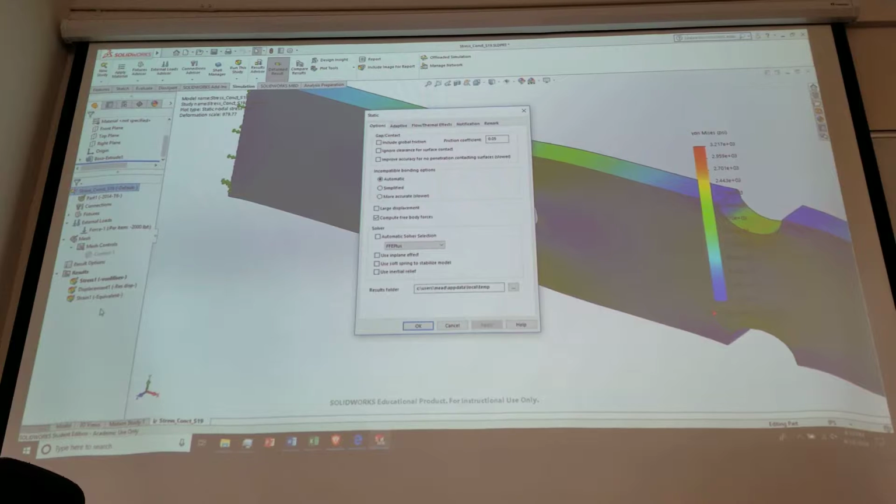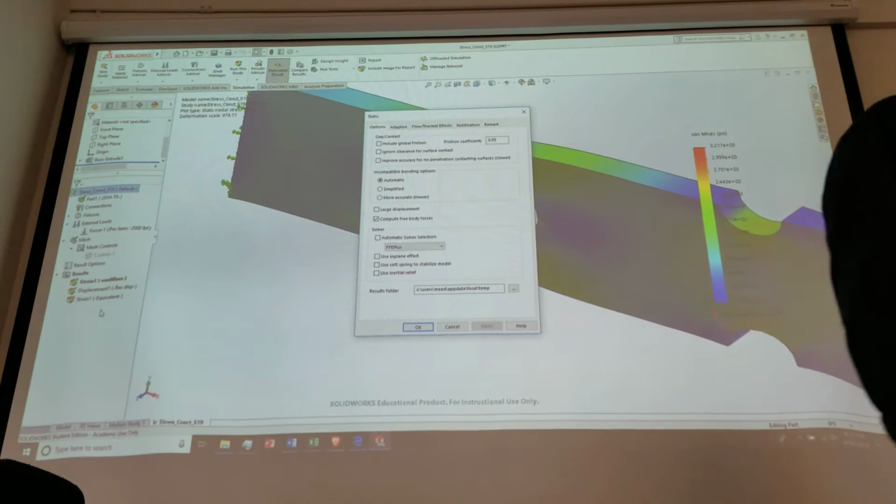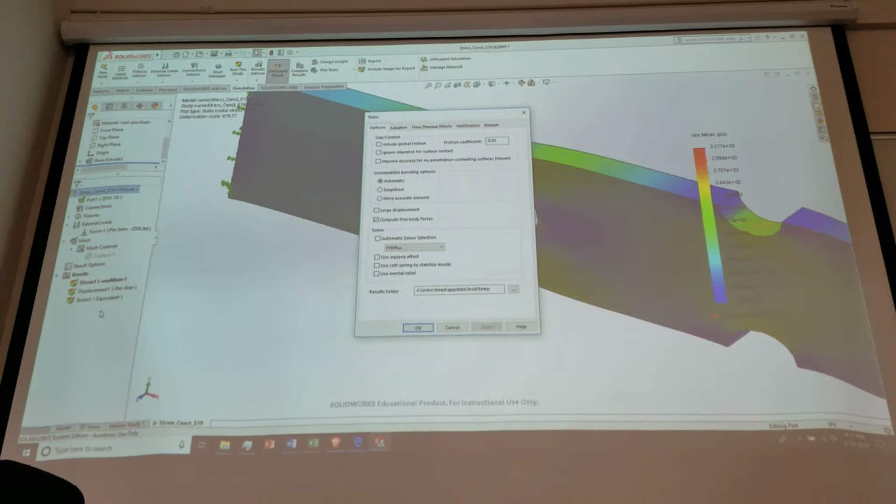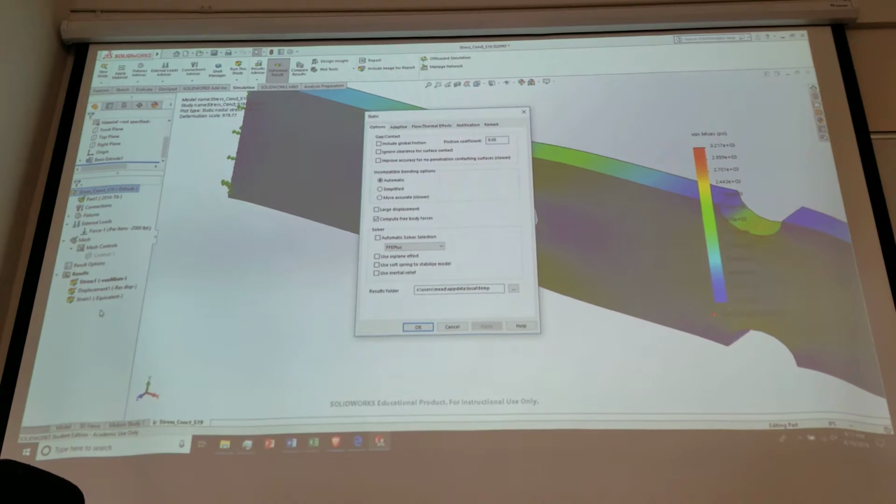Not guaranteed, but almost always. But it's not quite so badly failed that it's just given up, catastrophic. By the way, if you turn on the large displacement flag and let it run, it will run in the large displacement mode, and when you don't like the answer, the large displacement mode won't go away. Which leaves the question: what the devil is the large displacement mode?